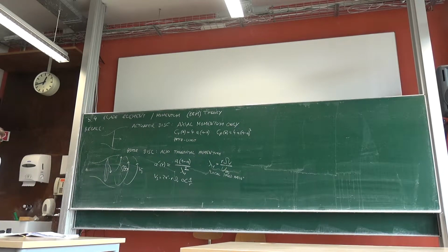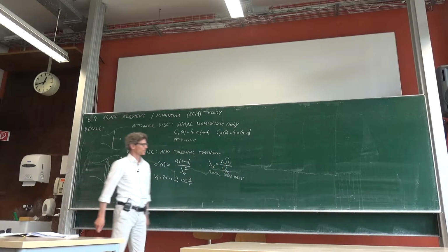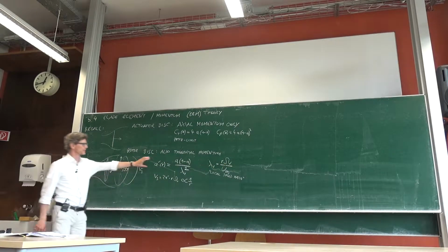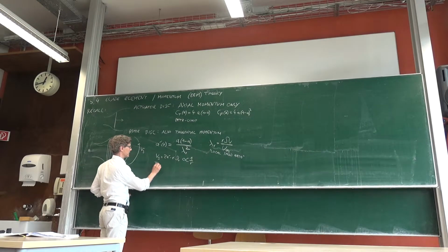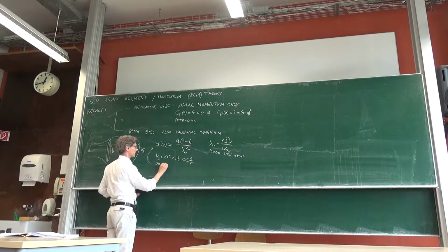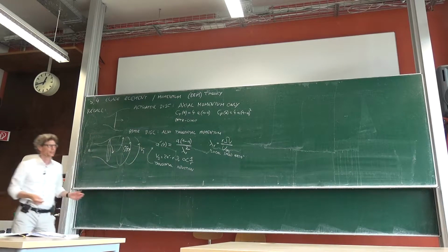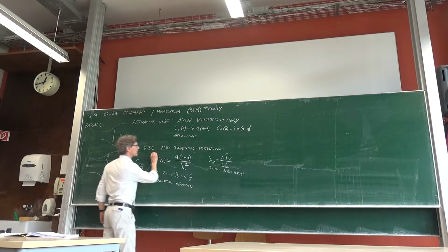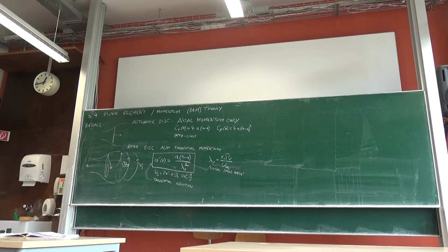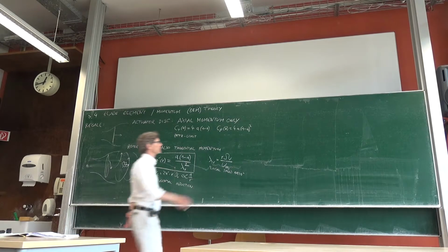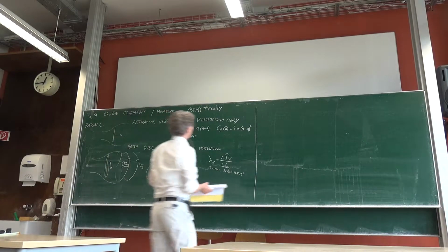And also, what we should keep in mind is the faster we rotate, so the bigger this omega, our wind turbine rotation speed, the lower actually this induction, the tangential induction. So this is all already derived, and I don't want to derive it again, but maybe to remember this thing is basically the output of the tangential momentum theory. And what we want to do now is BEM, blade element momentum theory.